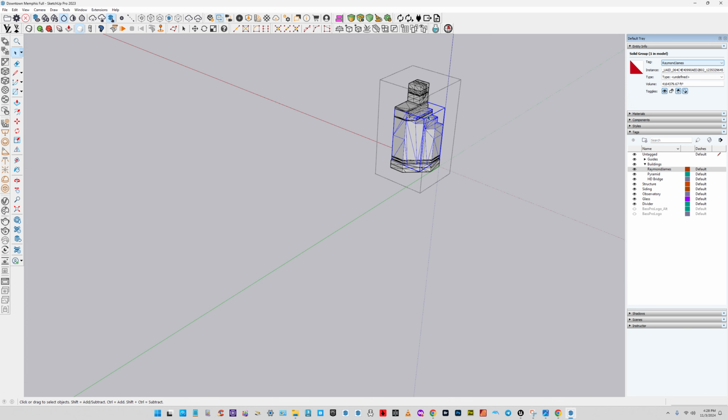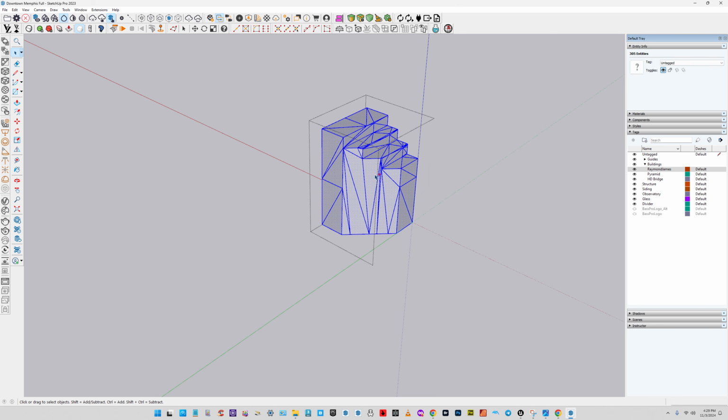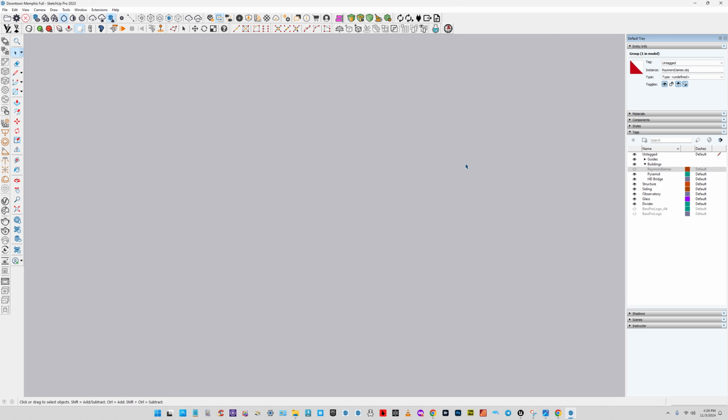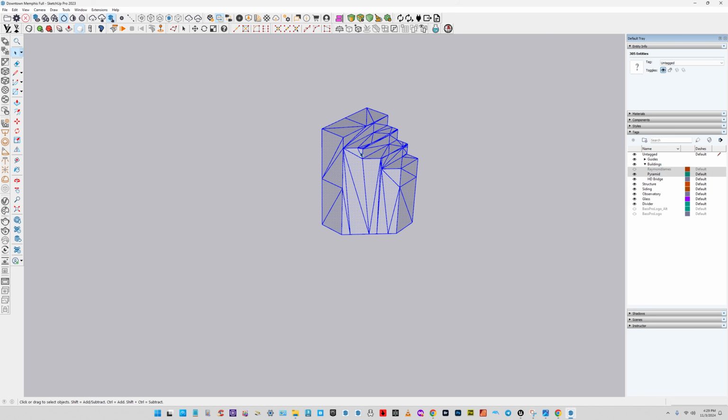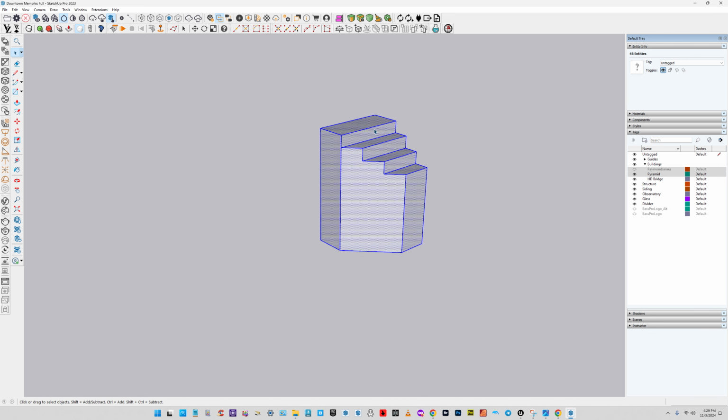When we double click into it, we now have all individual bounding blocks for those assets we created in Unreal Engine. So for example, I can now go in here, Control A, copy, close out this group and hide Raymond James, and then do a Control Shift paste, and then a Control Shift C to clean that model up. Basically, I'm using Tools, Extensions, Cleanup 3, and I have clean with last settings set to Control Shift C. All right, clean those faces up,